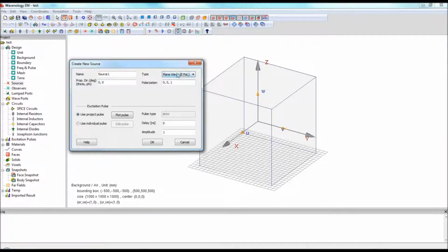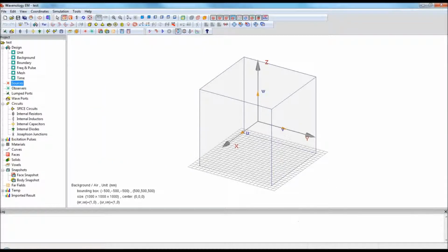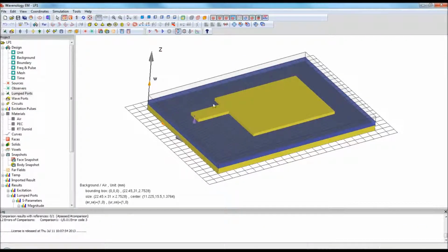As you select different types of the source, you will see the parameters it's asking for change. It has some more control parameters, and for the near-field ingestion, you can specify files as well. Once you select this type, in the other section of the dialog, it always shows you what kind of signal you're going to apply to this type of source. Here, I'm assuming that you've watched the video tutorial about our source signal, the transient signal tutorial. Okay. So let's get started with the first source, the lump port source.